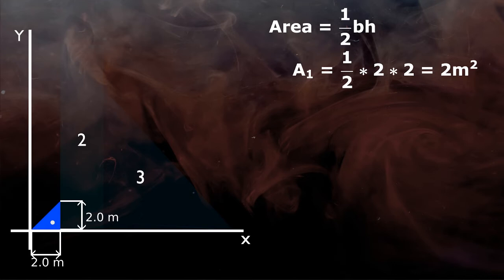The most important step is to find the x and y coordinates of individual shapes. If you know how to find them correctly, the problem of centroid is very easy to solve. As we know, the x coordinate for this kind of position of triangle is 2 multiplied by width divided by 3.